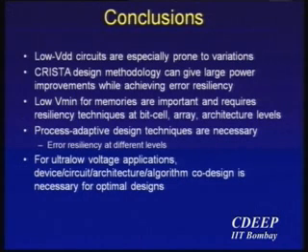And process adaptive designs, it doesn't matter if it's silicon, it turns out are going to be important for other scaled technologies. If you think of the fact that I'm going to be using FinFETs and a very thin body transistor, a thin body transistor might actually suffer from variation of the body thickness. And those of you who are familiar with it, the quantum confinement effect can actually change the threshold voltage of such devices. So if you have a 6 nanometer device versus a 7 nanometer device, there can be a good amount of variation in the threshold voltage due to quantum effects. Even though it's an undoped body, because of the very thin body, thickness variation is going to give you a large VT variation. So unless you have a device with about 10 to 11 nanometer wider body, which is possible to do. Those are the kinds of things that one has to look at. But then again, there are weak quantization effects and all kinds of other things.